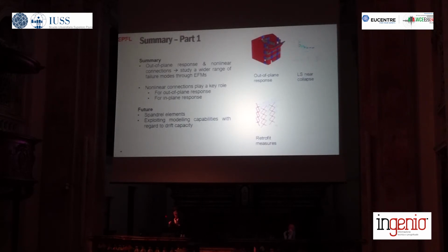As I said, the nonlinear connections play a key role for the out-of-plane response, in fact also a bit for the in-plane response, in particular for the in-plane response of spandrels, because with the nonlinear connections we can now really allow the elongation of the spandrels depending on the diaphragm stiffness and the effective connection.